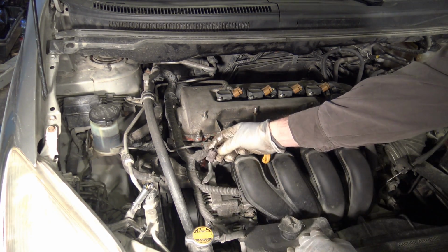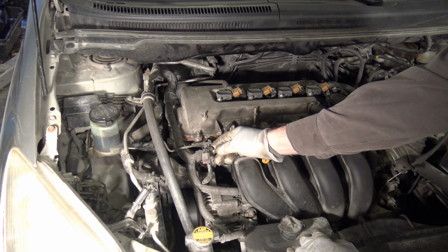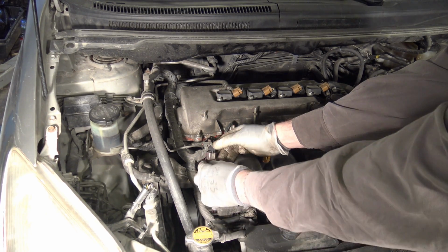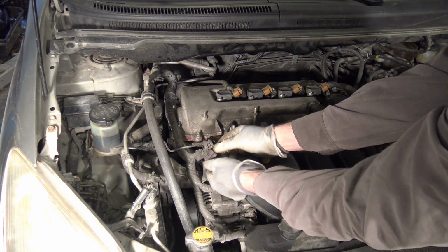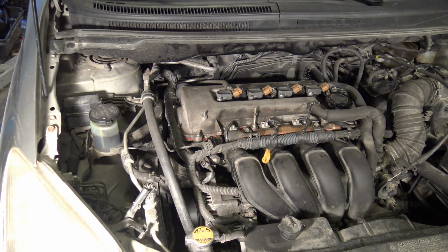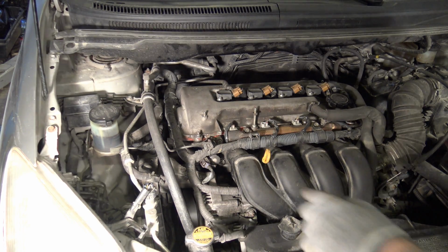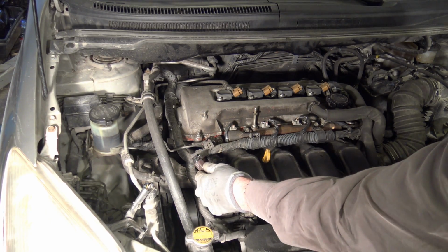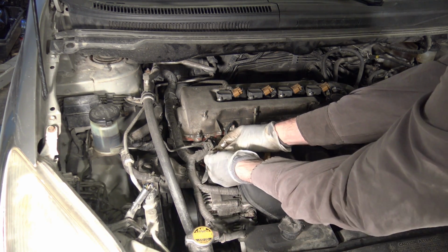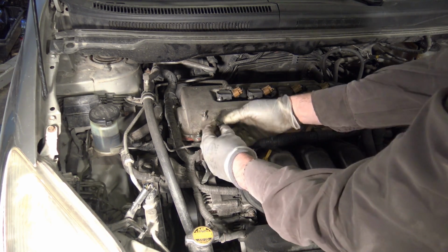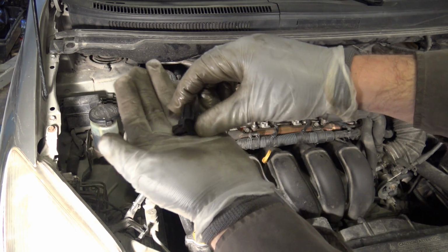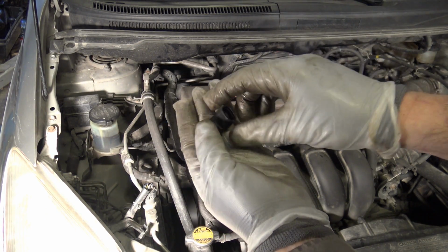There actually happened an electric connector failure, and now I can press this connector, because this connector belongs in here in that position, and now when I look, it is cut and broken in here, so I first take that connector away, and this is now the issue why my VVTi is broken.